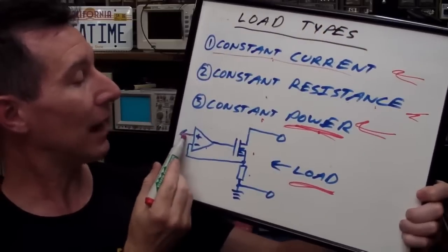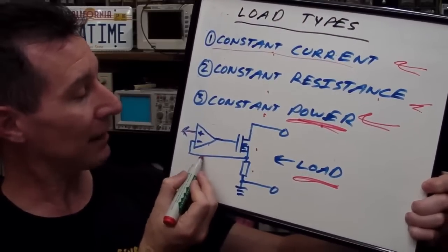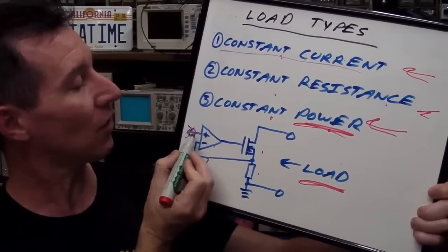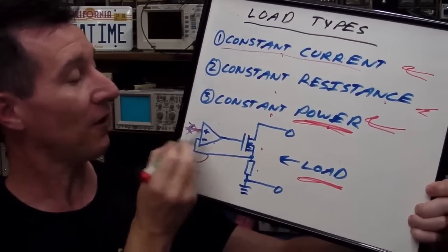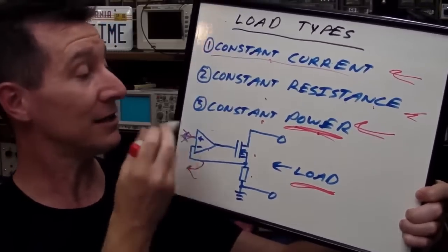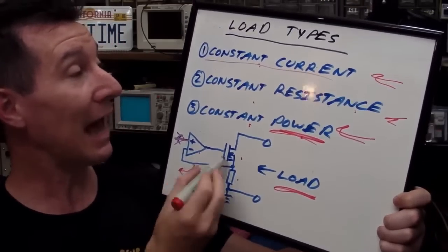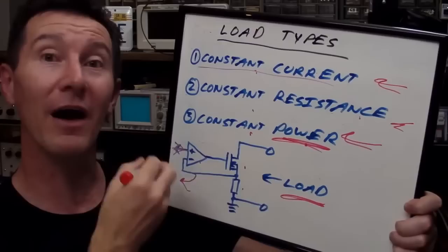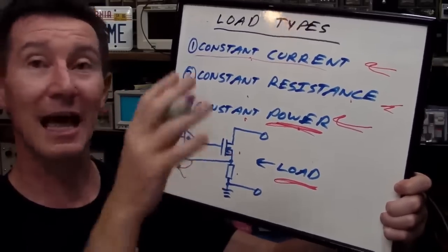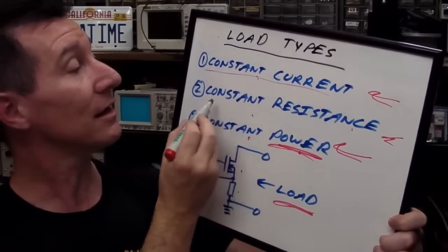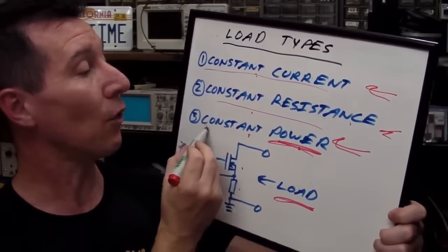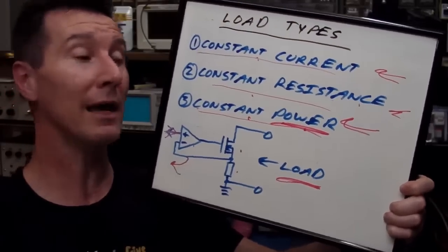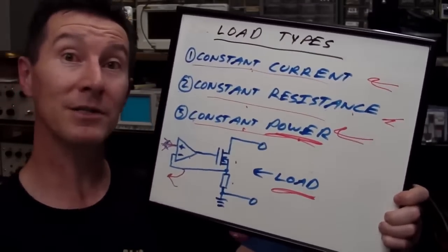But if you feed the voltage back to a microcontroller and you actually control the input via a DAC, so if you use an intelligent micro in there, by doing some simple Ohm's law calculations on the fly and changing this as the thing discharges, you can generate a constant resistance or a constant power in this load. So this is a pretty handy way to measure battery capacity.